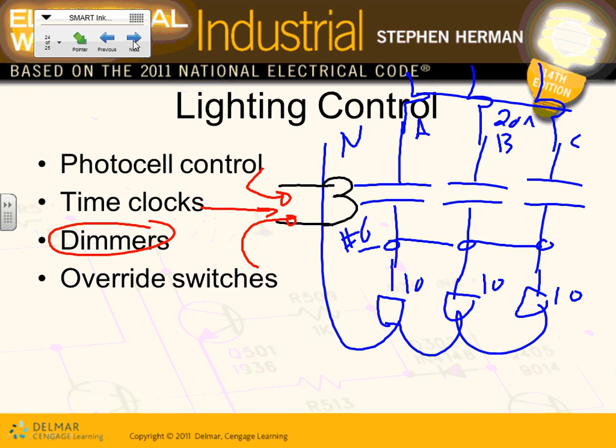So really photocell control or time clock, and astronomical clock is another option to control these magnetic contactors. Or you can have just a contactor. This is the big spiel, 3-phase. You can make just a single phase, one phase on a timer that controls that particular phase. Any comments, any questions?